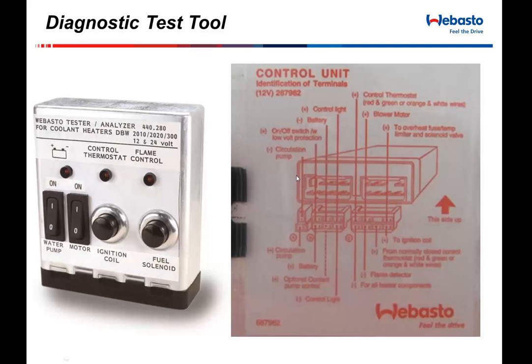On the front of it is a label that shows which each individual pin is responsible for. I know it's a little bit difficult to see, but the main battery input is coming in onto what we refer to as B4. I already know that I have power at B4 because my idiot light over here came on when I hooked it up to the diagnostic test tool.